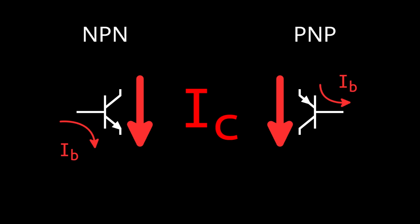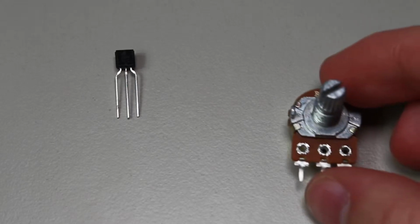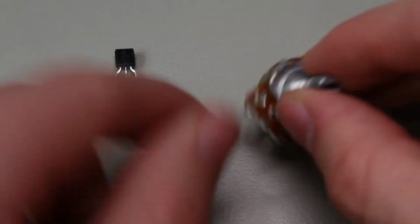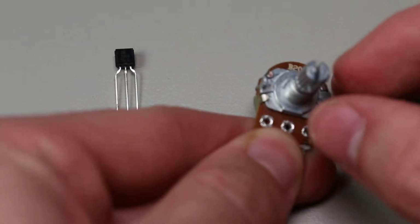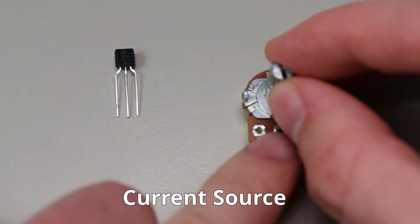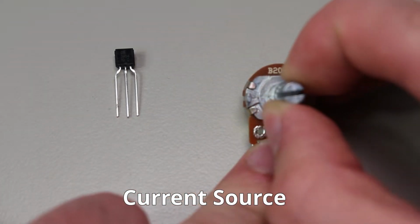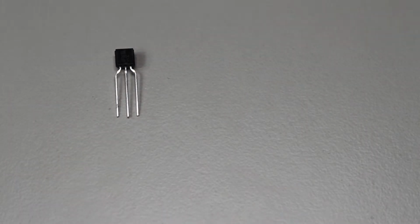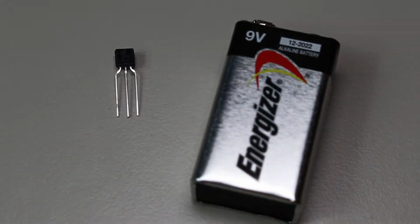To better understand how this all works, let's draw a parallel to another real-life component. Some people will tell you that a BJT acts like a variable resistor, but that oversimplifies everything. Instead, I encourage you to think of a BJT as a current source. A current source is a component that will maintain a constant current across its pins so long as enough voltage is provided. It's similar to a voltage source, which maintains a constant voltage.